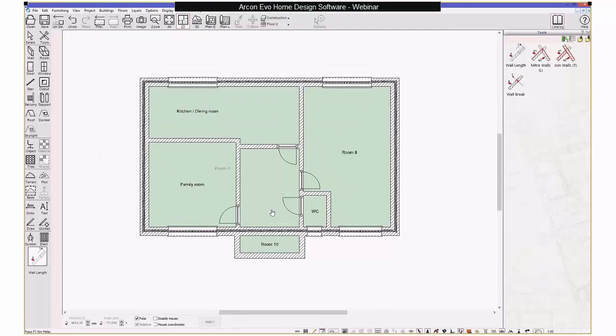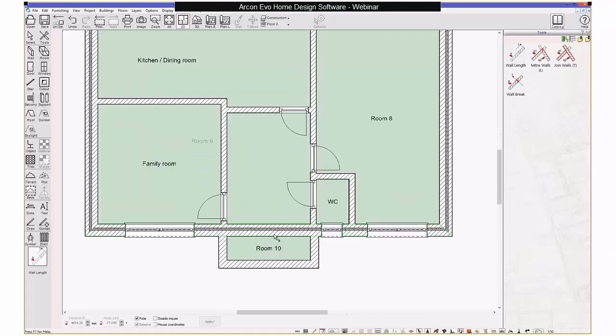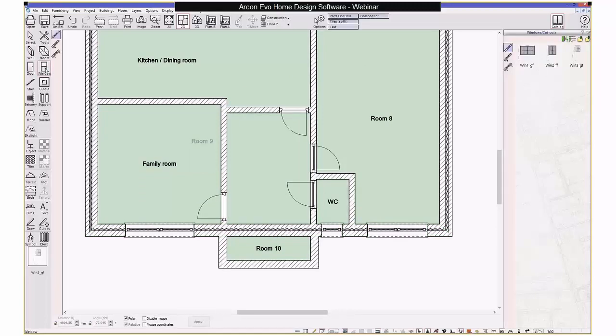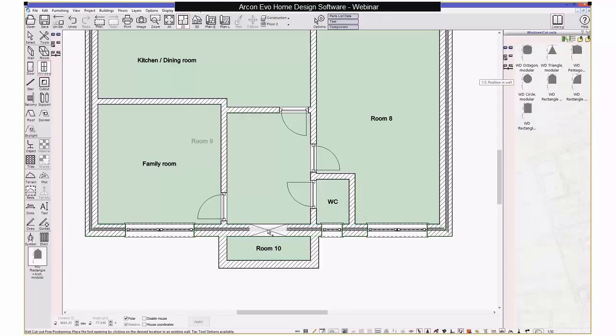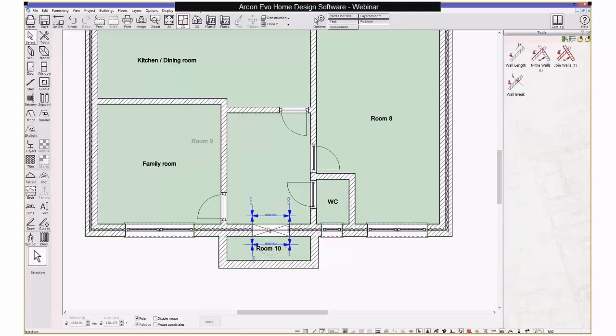Okay, and I'm just going to create a cutout within this interior wall here. So I'm just going to click on the Windows folder here, and then I'm going to go to the cutout section here. Go to openings, and I'll click on this arched option here, and just place that in position there. And then I'm going to click on here, open up my component editor.